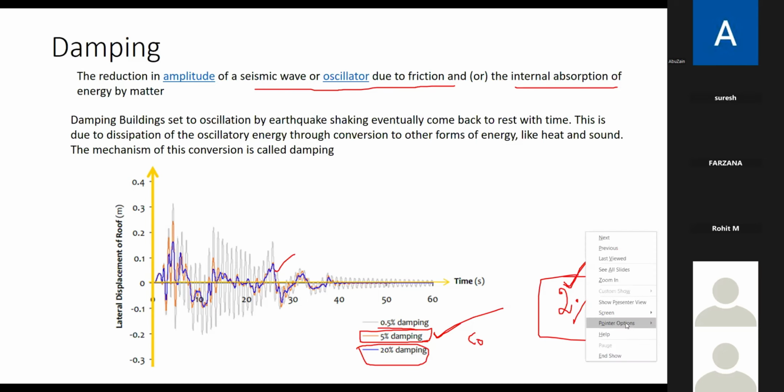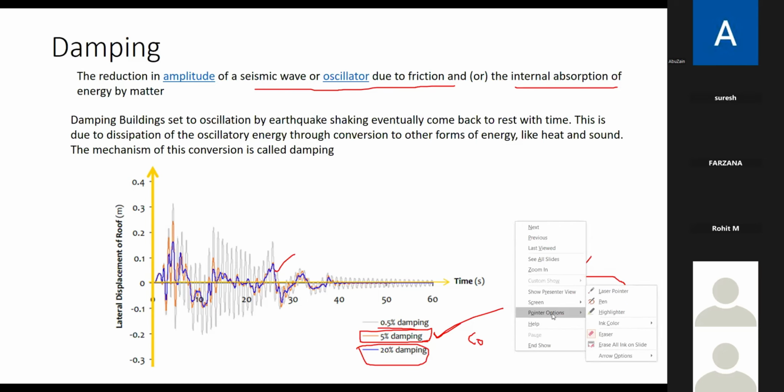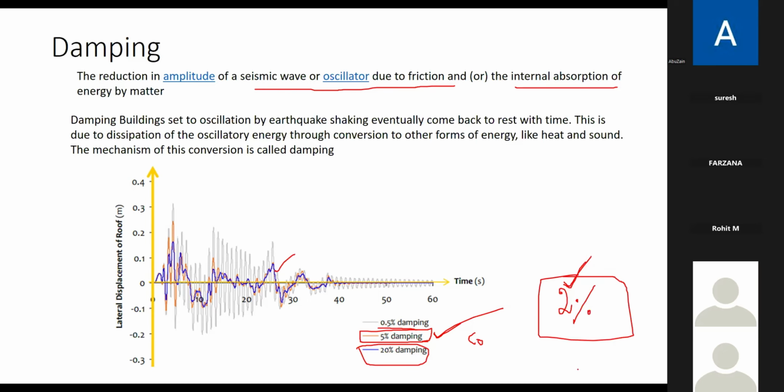But now the question comes: if the building is torsionally irregular, you mean to say I cannot design it? Whatever buildings we see with different shapes, 100% that is torsionally irregular, right? I cannot go and dump stiffness. I cannot build the complete building as shear wall, huge stiffness, because you would spoil the architectural aesthetic view or even architectural utilities. In that case, you can design a torsional irregularity, but you have to increase the damping.